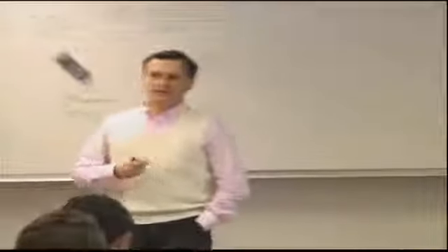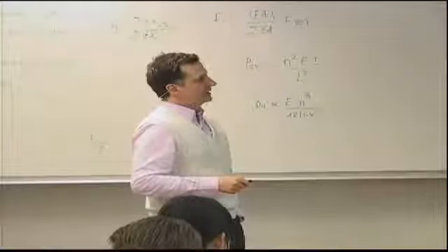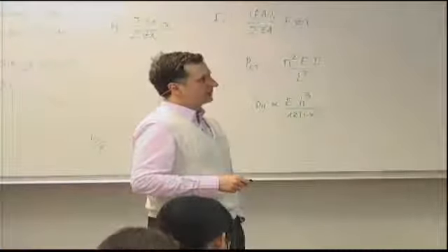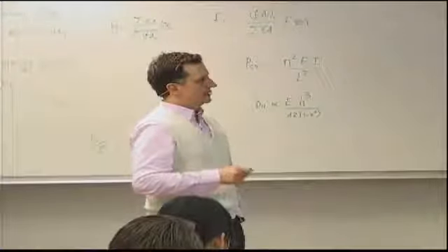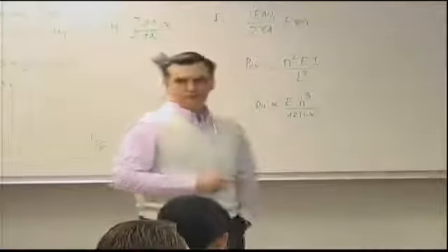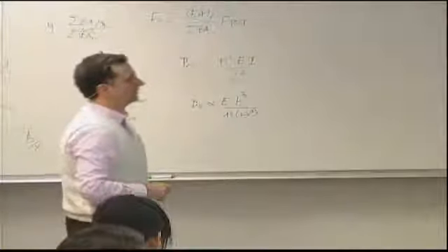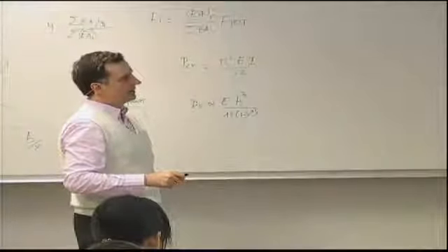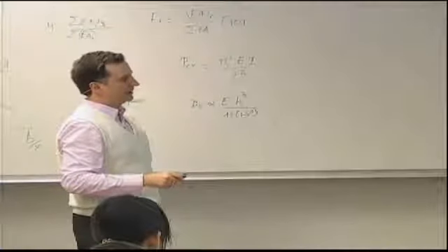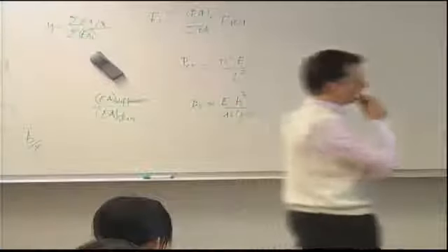And as I was saying, that may not really be what's happening. It turns out test results suggest that if you have countersunk fasteners or rivets, then this equation here is pretty close to test results. You can adjust it based on test results and the type of countersinking and so on, but in general this is good enough. So if I put in a constant C and I set it equal to 1 for countersunk fasteners, I would get a very good prediction using this equation. If I set it equal to 3, I would get the story of the protruding head fasteners.